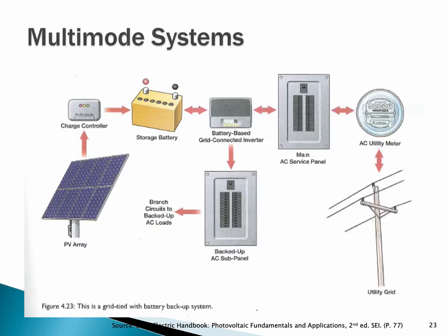Multi-mode systems, we talked about these. We have an inverter that can operate standalone as well as with the utility. We have battery backup on site for meeting loads that are needed, and those critical loads are running 24 hours a day, whether the grid is present or not.